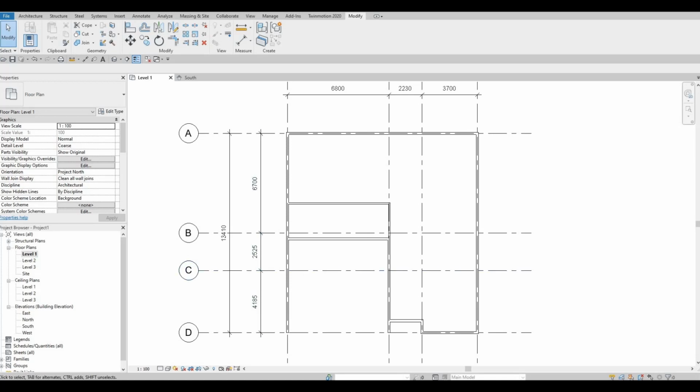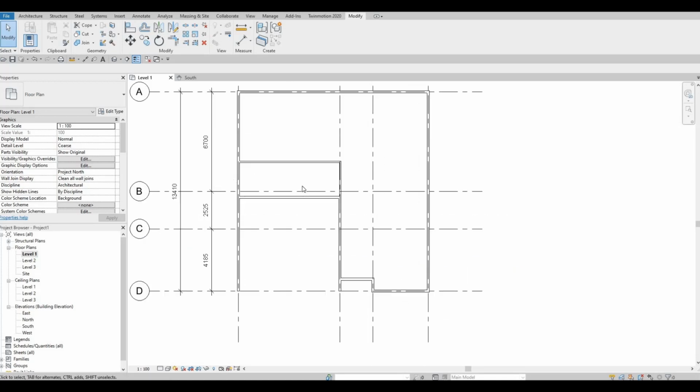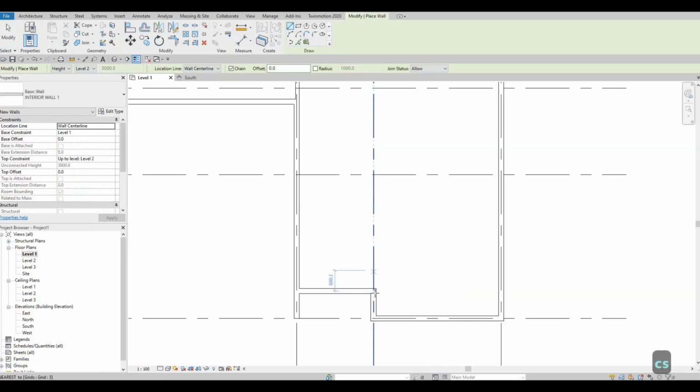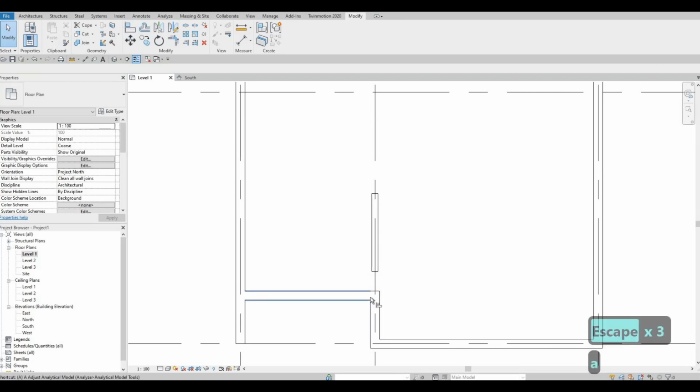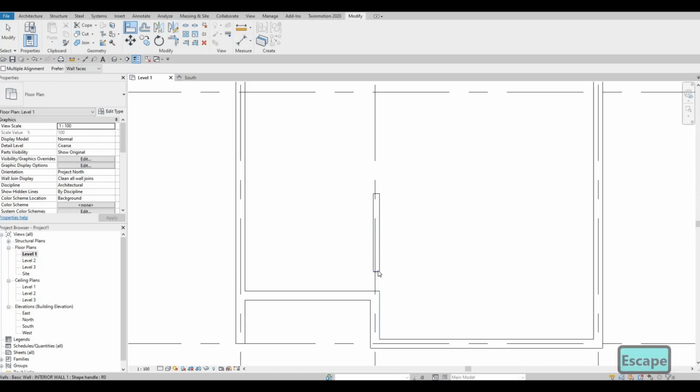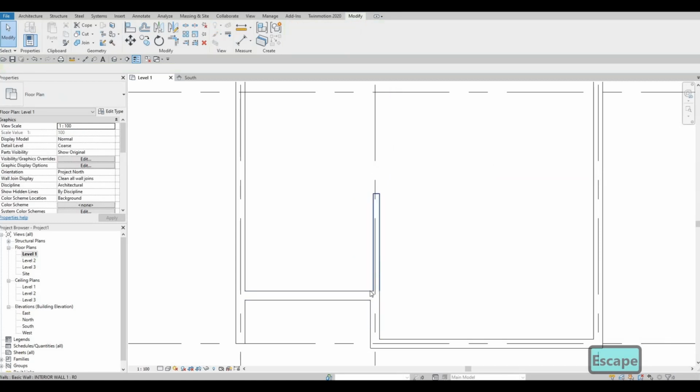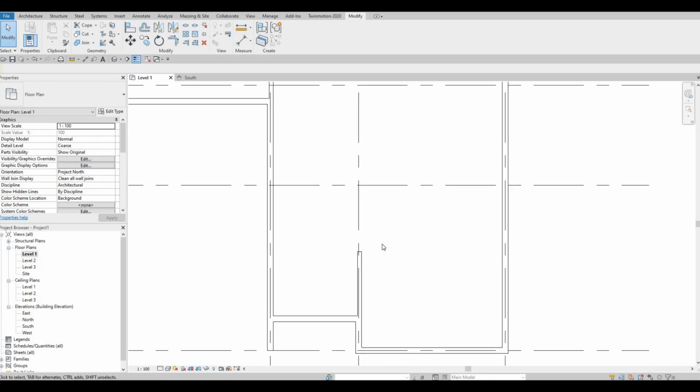And then we need to add in a wall right here. So click on the interior wall, CS. Don't connect them yet. Same idea here because of the thickness of the wall. So type in AL, that's the align command, this face to this face. Press escape and then now connect them all together. And you don't have to worry about the indentions of those.